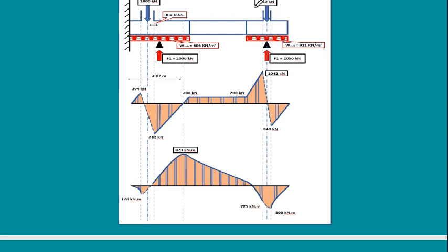This here is the beam. It is supported on this column and supported on this column. So this small portion is a cantilever, and this small portion is a cantilever. I can easily calculate this value and this value. These are the bending moments on the cantilevers. But now I need to calculate the bending moment inside. I don't know where the location of the maximum moment is.